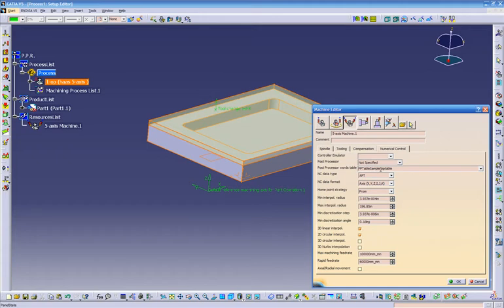So I always use the PP table sample, and your output is going to be a APT. Most of the best Catia output, it's APT. And if you have a host machine, there are companies out there that will take the APT and convert it into NC or whatever your machine can read. So for now, we're gonna just create APT only. Okay.